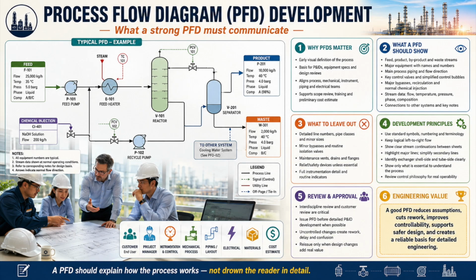Special process requirements should be captured through clear notes. This may include operating constraints, required elevations, gravity flow conditions, minimum static head, vapor disengagement requirements, mixing limitations, exchanger arrangement, phase separation requirements, or package interface conditions. Where licensed technology is involved, include the required confidentiality statements and restrictions.